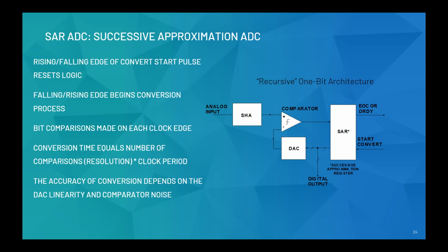If you note, this ADC architecture requires a held DC voltage, which we see in the block labeled SHA. You can imagine that the main disadvantage of this type of architecture is that the sample rate depends upon the resolution. If you have more comparisons to do, more resolution, it's going to be more time consuming. So I think those are the key points, just to summarize how this basically works.